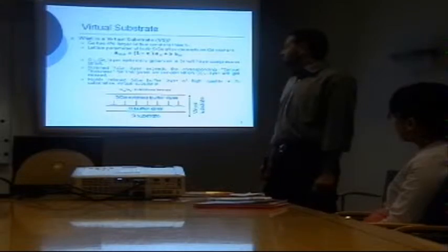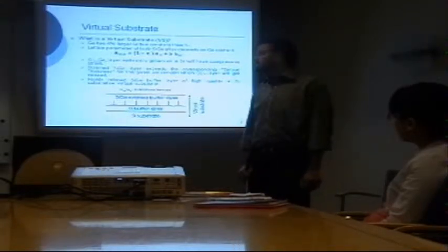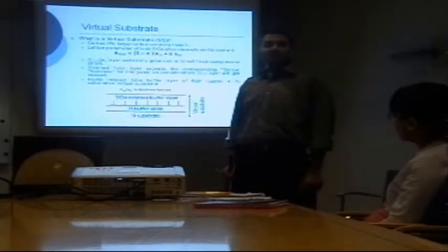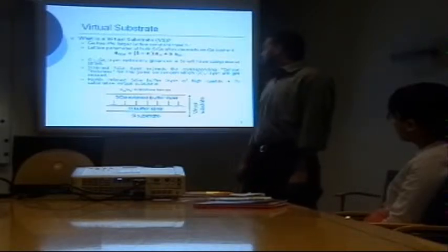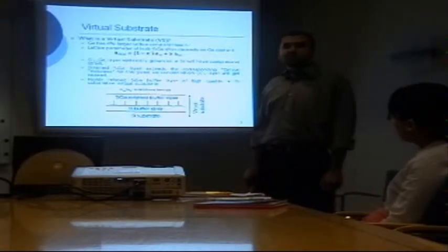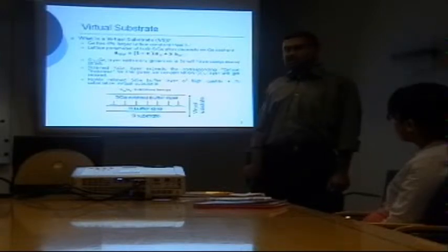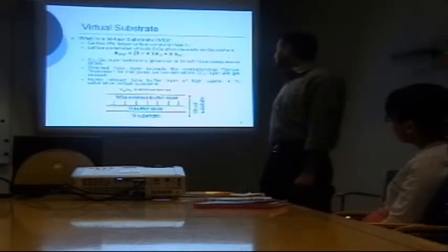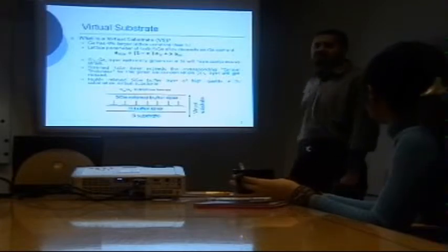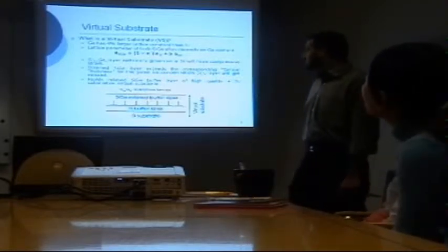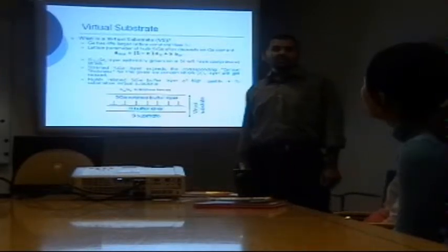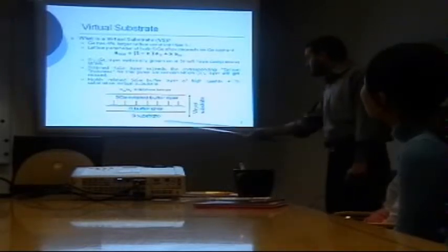First, I'll define the virtual substrate. As we know, germanium has a 4% larger lattice constant than silicon. And the lattice parameter for bulk silicon germanium alloy depends upon the germanium content, which we can calculate using Vegard's law. If we grow this silicon germanium layer on silicon, it will have a compressive strain. And when this strained silicon germanium layer exceeds the corresponding critical thickness for the given germanium concentration, the layer will get relaxed. So the whole structure having a highly relaxed silicon germanium buffer layer of high quality plus the silicon substrate will be called a virtual substrate, as you can see in this figure.